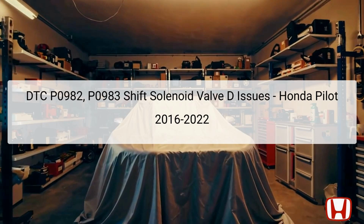The Honda Pilot from model years 2016 to 2022 may face diagnostic trouble codes DTC P0982 and P0983, which specifically indicate issues with the Shift Solenoid Valve D. These DTCs can indicate two core problems. P0982 signifies a low input from the Shift Solenoid Valve D, while P0983 signifies a high input.